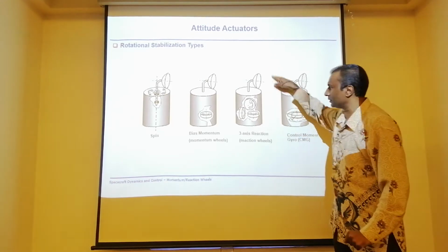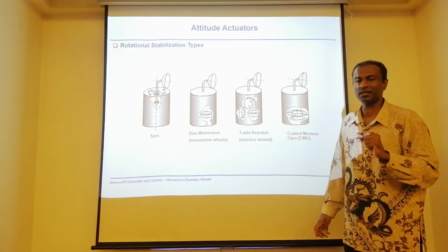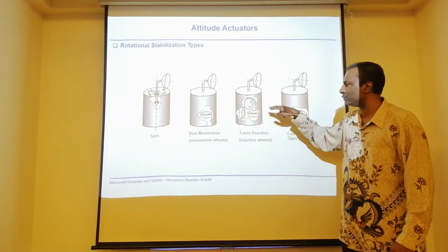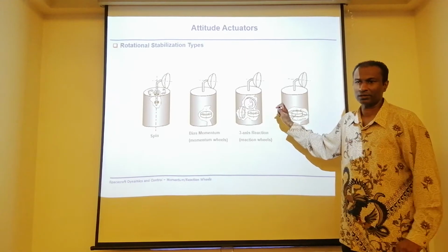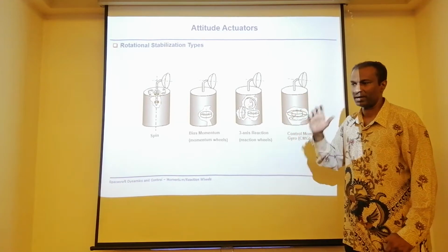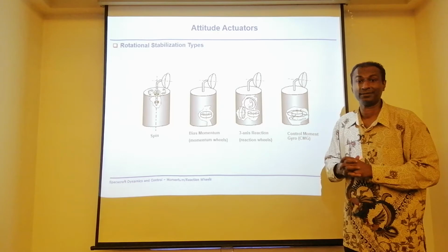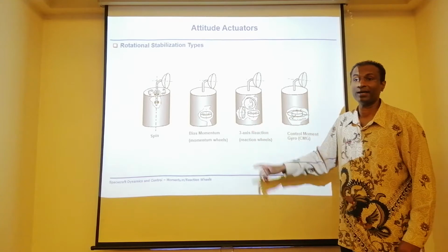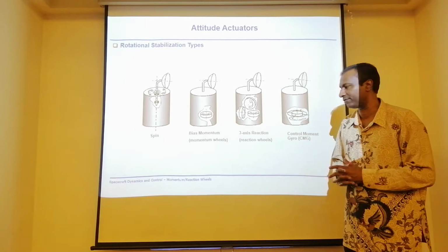Now attention, all those very precise pointing satellites, expensive as well, you will see that more often than not, they come with 3-axis pointing. Using reaction wheels will be one of the most common options. You want to have an Earth observation mission. Let's say you have calculated all those Earth observation exercises. All those Earth observation satellites, more often than not, will be flying with reaction wheels, because reaction wheels will give you good attitude performance, just like what we have seen before.